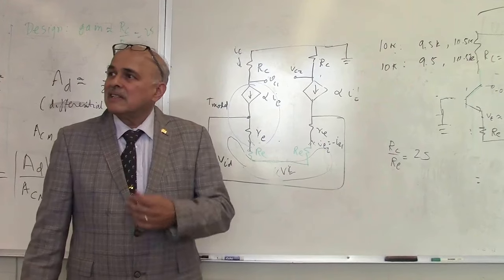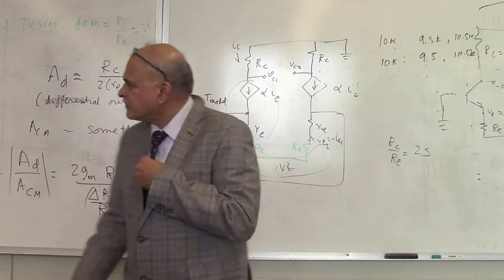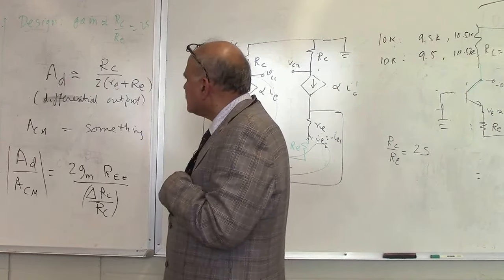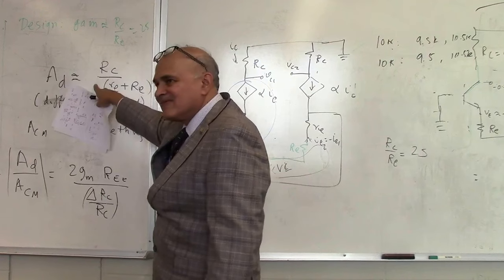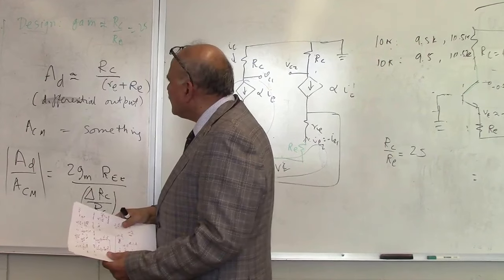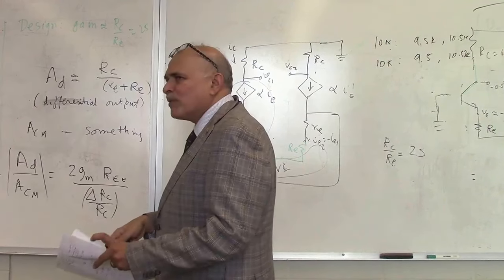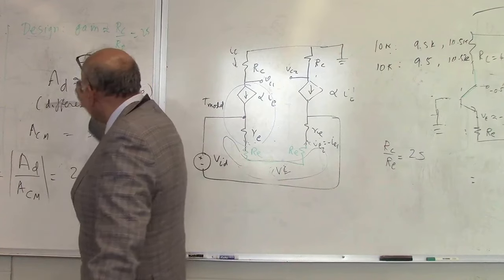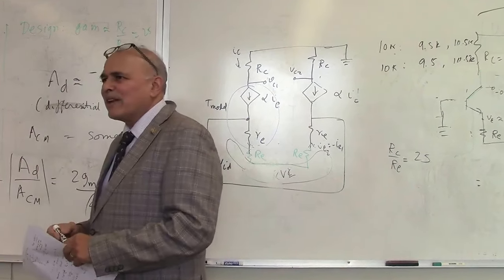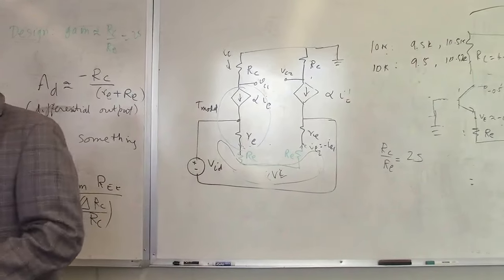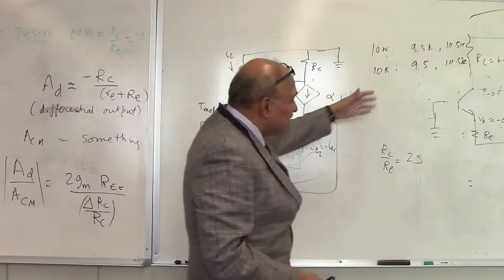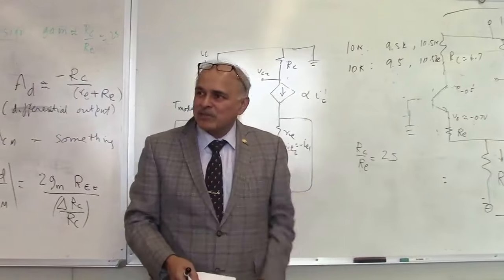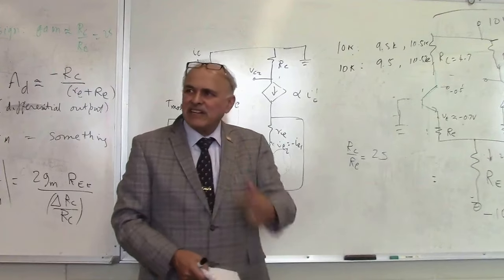Yes? The differential output gain, that's for the single side, right? No, differential is double-sided. I think. Oh, I'm so sorry. And it's negative, right? Oh yeah, that's true. Probably if you say VC1 minus VC2. Of course, here we are only asking you for magnitudes. But correct, thank you. Yes, we forgot that the differential gain was the 2 would disappear. Yes, that was a single side.